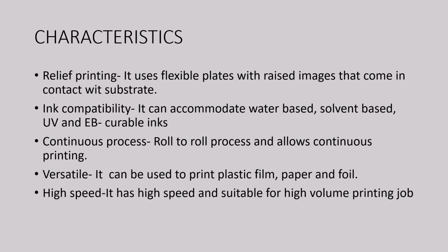Now, the characteristics. Relief printing: it uses flexible plates with raised images to print on the surface. As the images are raised, they can be transferred easily onto the substrate surface. Then compatibility: you can use any kind of ink, whether it is water-based or solvent-based, UV or biodegradable inks, in the flexographic printing process.